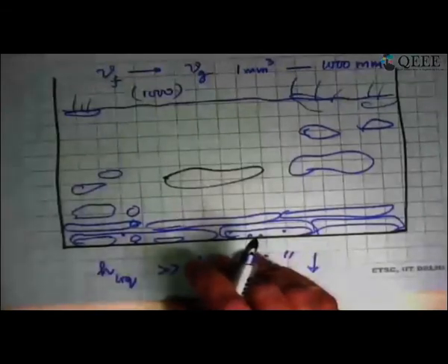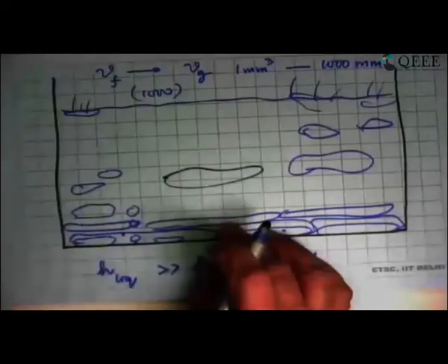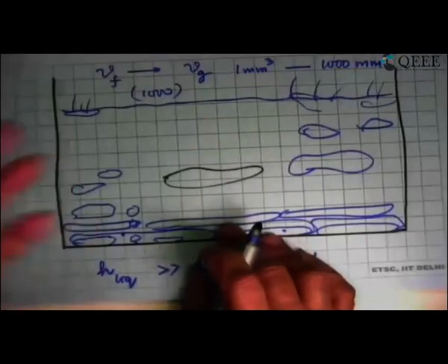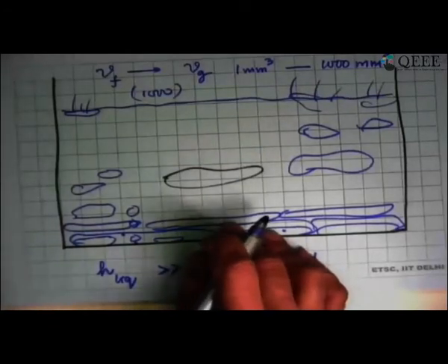The volume increases that much, which is why this vapor, although it looks big in size, in terms of mass, is very small, and the rate at which mass was converted from liquid to vapor multiplied by HFG, that becomes small, so the heat transfer coefficient becomes small. That's what we are seeing happen over here.